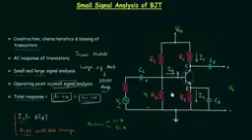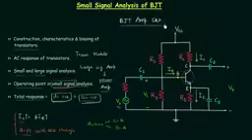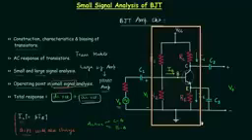And for this we must have a clear idea about this circuit. This circuit is a BJT amplifier circuit. The portion of the circuit inside the rectangle is voltage divider bias. We have already completed voltage divider bias in the previous chapter. Actually we have this whole circuit, but in DC analysis we only have to consider the portion of the circuit inside the rectangle, because C1 and C2 will act as open circuit and the portion outside the rectangle will not be included in the DC analysis.